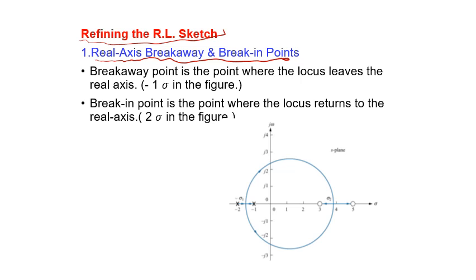If you remember this graph, this root locus, which we discussed earlier, we said there is a 0 here, a pole here, and a pole here. When I draw the root locus for it, we will find a real axis segment here and another real axis segment. So it's very clear that with two poles and two zeros, they are going to meet on the S-plane, with nothing going to infinity. One pole will go to one 0, the other pole will go to the other 0. That's to be kept in mind.